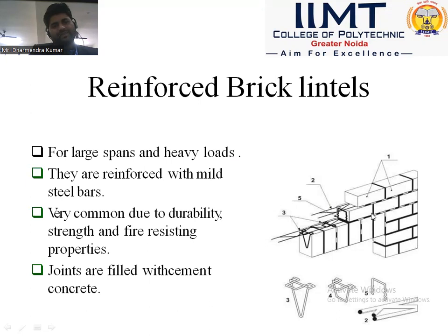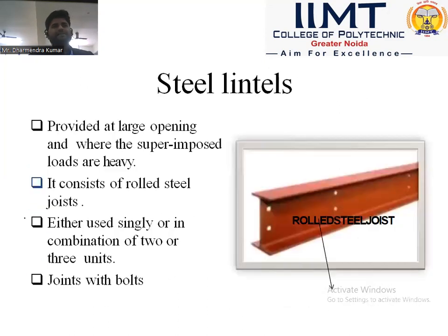You can see this is the combination of steel and brick, and we can also fill concrete in the gap between brick and reinforcement. So you can see in this diagram, this is the commonly used lintel. This is called the reinforced brick lintel, and this is very useful for durability and strength.